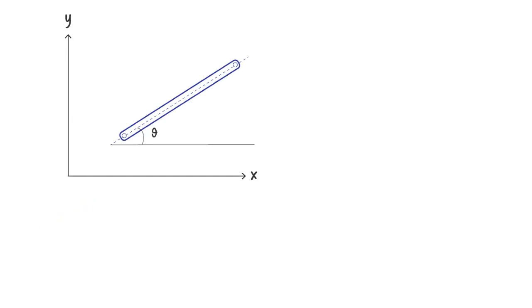Let's take a look. In the local coordinate system, we labeled the displacement at this end as u2. In the global coordinate system, the same end displacement is labeled d3 and d4. This means the projection of d3 onto this axis plus the projection of d4 onto the same axis adds up to u2.